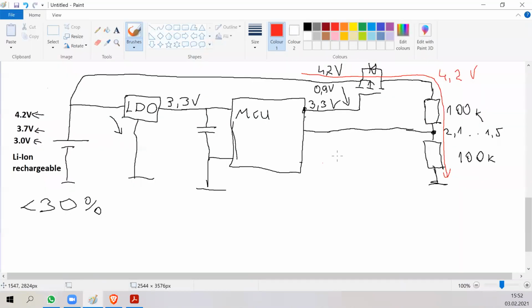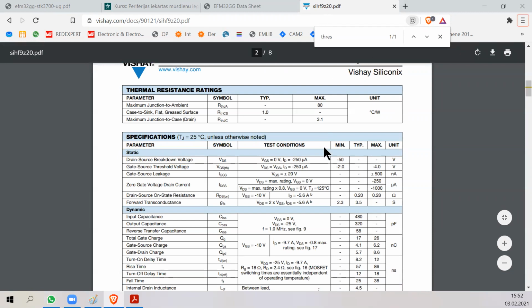Minus because the direction is usually from drain to source in N-channel, and in P-channel everything is opposite. You connect it in an opposite manner, so the current is also negative. It's just a technicality. But basically, at -2 volts, it's -250 microamps. At -0.9 volts, it will be something like maybe a quarter of it.